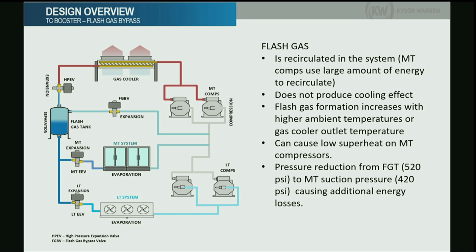Real quick on the flash gas bypass valve, we're reducing the pressure on the flash tank. Technically, if that flash tank is at 520, we're running a temperature of about 35 degrees. Isn't that also helping to desuperheat the discharge gas of the low temp compressors? Yes, it does.